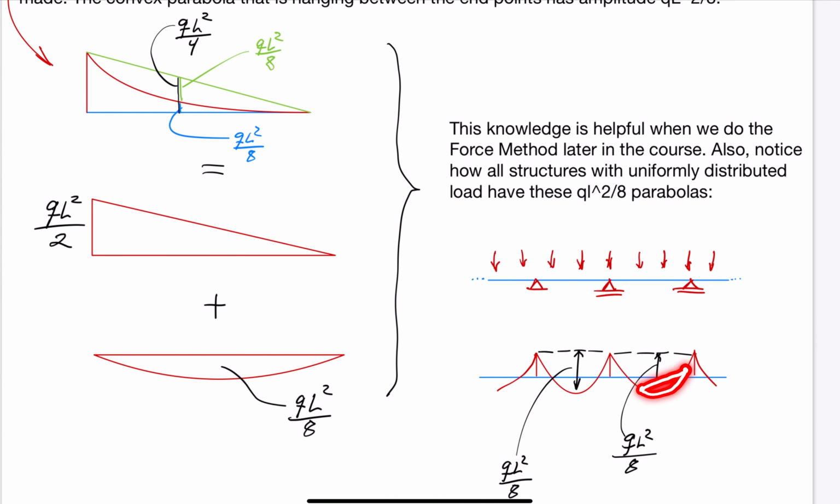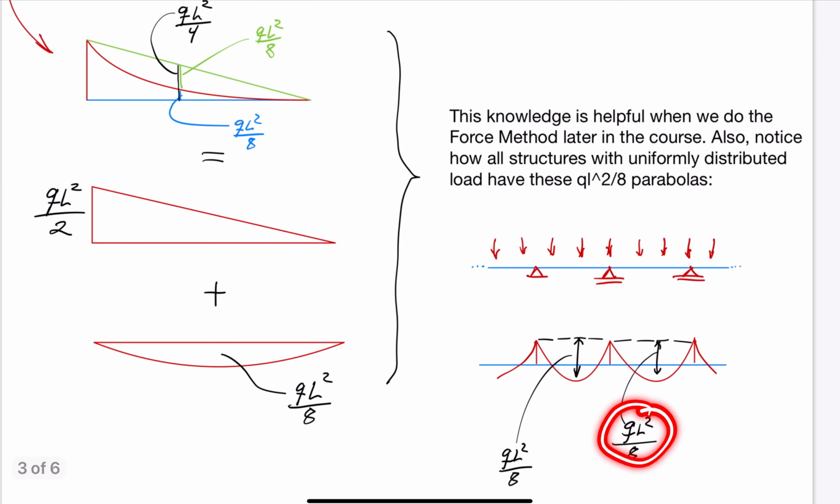What we have now seen is one reason why structural engineers sometimes use the value QL²/8 without more detailed analysis, because the bending moment value in a continuous beam cannot exceed QL²/8. The single exception is cantilevered beams, which we addressed above, which has a bending moment value at the base equal to QL²/2.